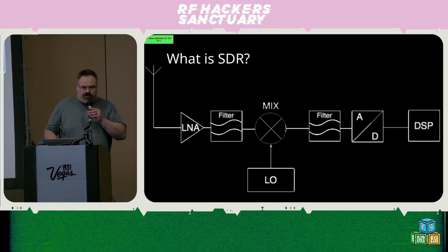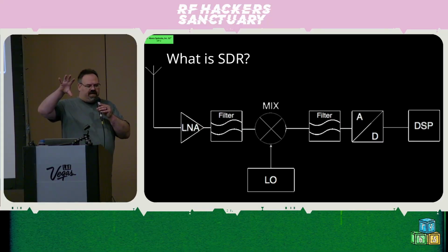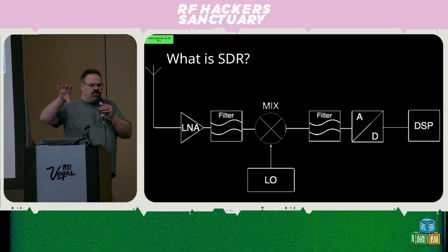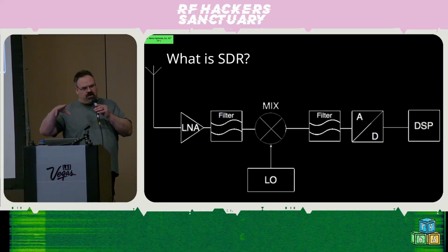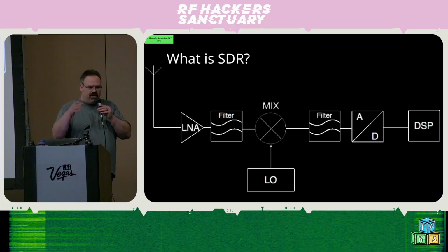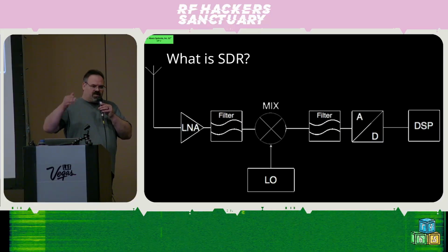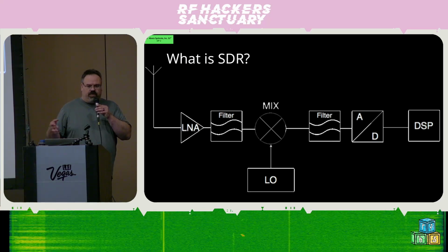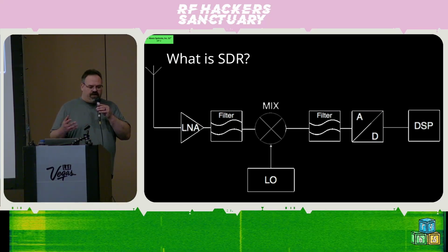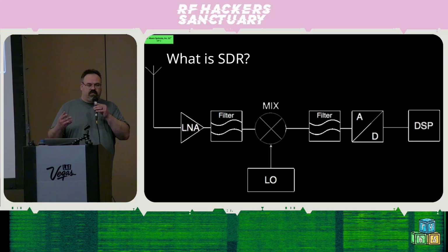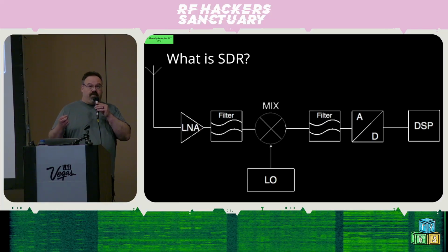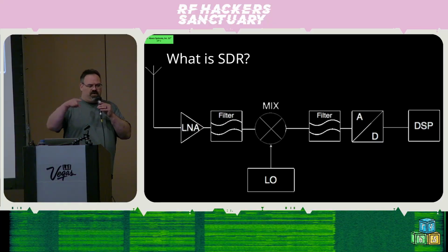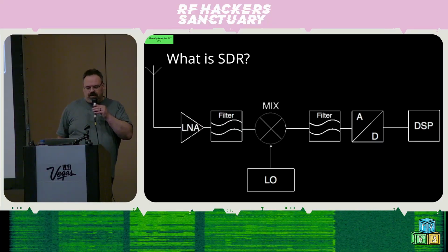So this is really handy if you have a device that is only set up for a certain chunk of frequency range. For example, an analog to digital converter, which say can only receive from DC to 30 megahertz, but you want to shove a 600 megahertz signal into it. Well, you mix that with a 580 megahertz signal, and you end up with the output of 20 megahertz, which is within the 30 megahertz bandwidth of your analog to digital converter.